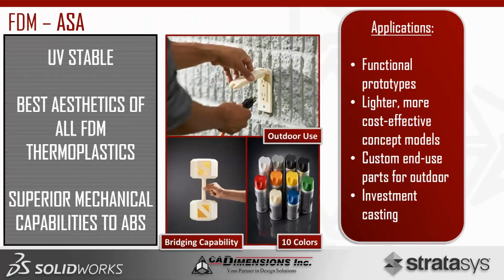So a couple things about this material. Right off the bat, it's UV stable, which isn't seen with most other materials in our catalog. It also has the best aesthetics of all FDM thermoplastics, meaning that just by the chemical composition of the material, it comes out looking as a high resolution. So the layer lines that you see on all types of 3D printing parts aren't as prevalent on ASA as opposed to some of the other thermoplastics.